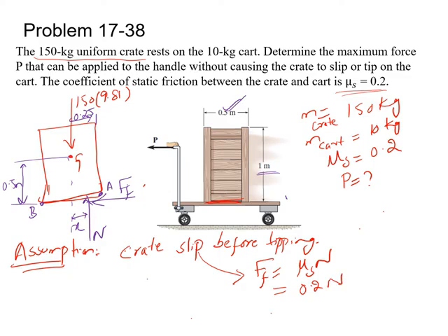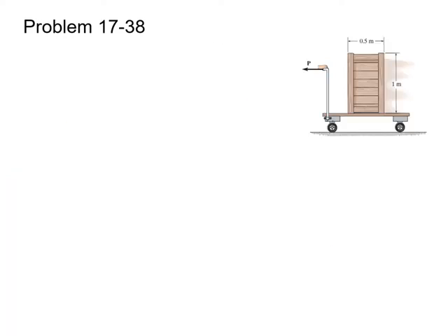Now after that we can apply the equation of motion on this rigid body. The free body diagram that I drew in the previous slide was this rigid body. On this rigid body, this was the center of gravity or center of mass on which the total weight mg is acting. Your normal force acts at a distance of x, and this was the friction force. This was all about the free body diagram.